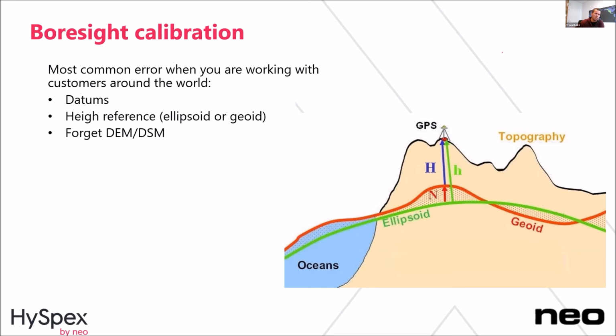That's locally very good relative to the country that you're in. For example, Svalbard has a very special one. And yes, you need to know that, right? So if we are processing with the HiSpec data in ellipsoid and the DEM in a geoid, for example, the normal EGM 2008 in Norway is 38 meters different from the ellipsoid.